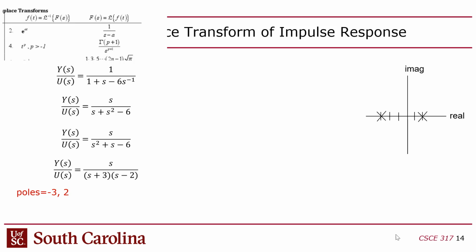It does a numerical solution. In other words, it approximates it using an algorithm, right? If you do an inverse Laplace transform, you're actually solving a closed form of it. You're converting this to another equation that you can plot easily, right? But you can't always do that inverse Laplace transform. You can do it in this simple case, as long as I can do some algebra to get it from this form into that form. Then you can calculate a closed form time domain representation of this S domain thing, right?